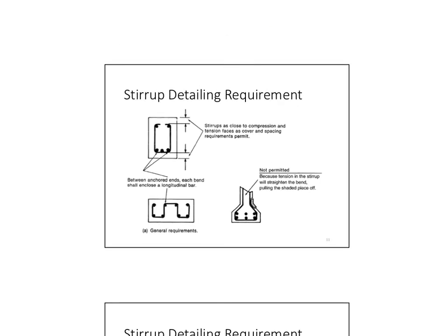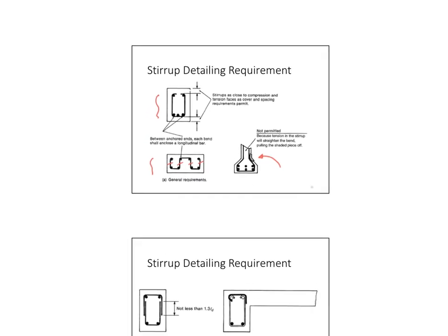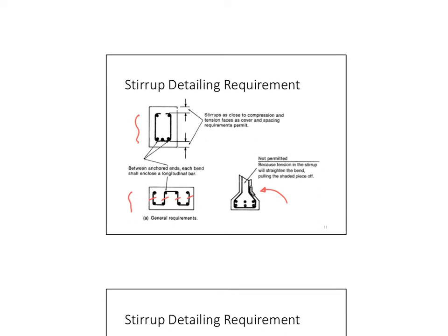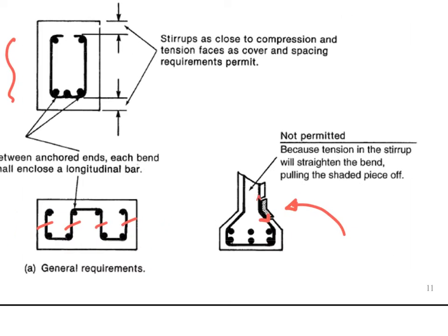Now these are normal other shapes. Now this is an open one, another open one. But generally speaking, looking at this one here, you have 4 legs, right? This is not a permitted way to do stirrups for bridge beams or eye girders, especially since with such a girder, the tension from this side and the tension from this side will end up in a resultant force this way, and this can spall out your concrete cover.